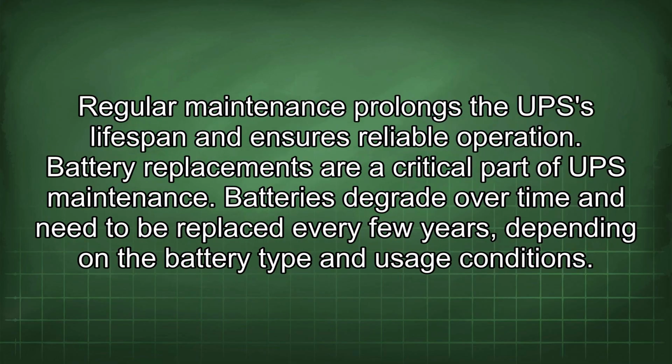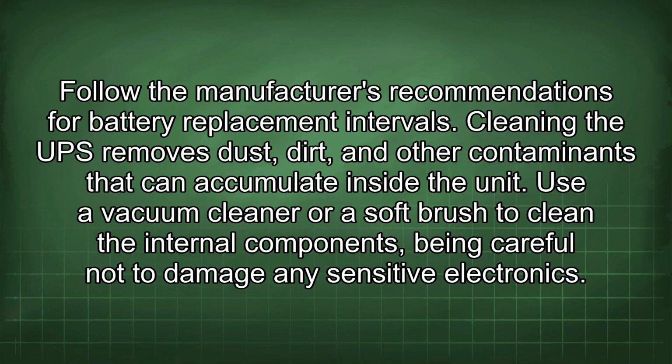Regular maintenance prolongs the UPS lifespan and ensures reliable operation. Battery replacements are a critical part of UPS maintenance. Batteries degrade over time and need to be replaced every few years depending on the battery type and usage conditions. Follow the manufacturer's recommendations for battery replacement intervals.